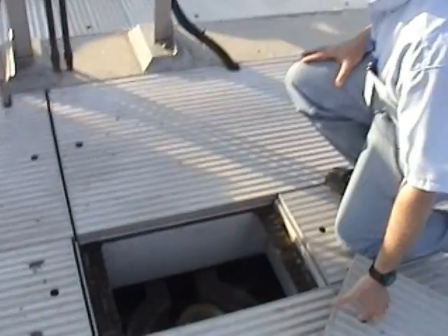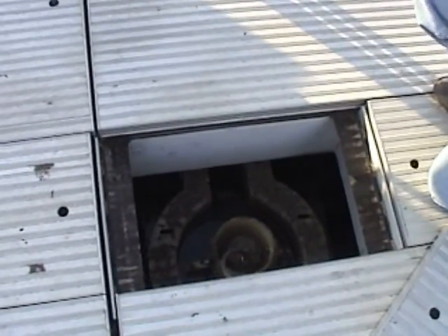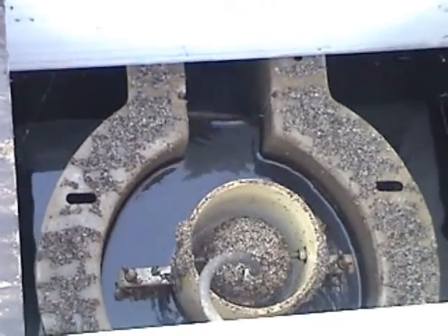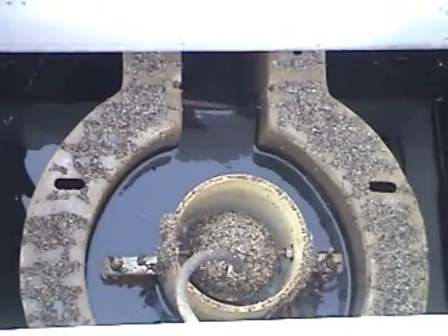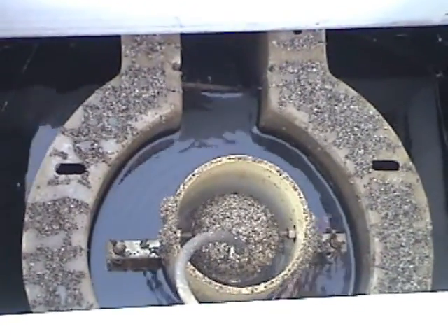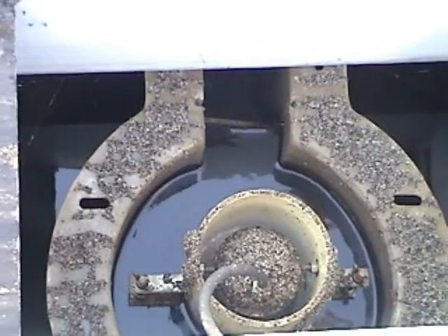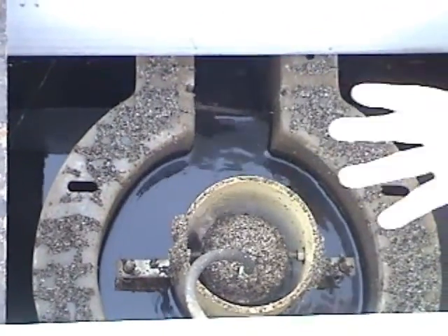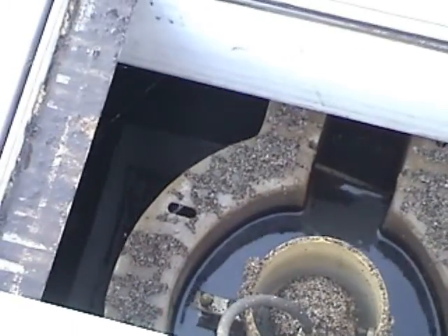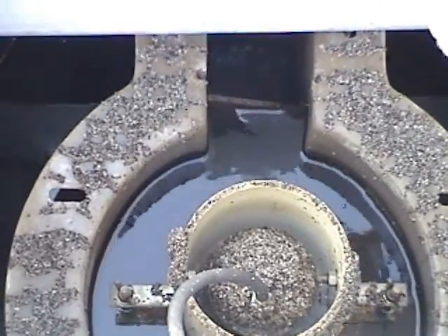What we're doing is we're taking our secondary effluent flow after we run it through the flocculators, where we add alum to it and mix it in, then we bring it over here and run it through a filter. And these are Dynasand filters, continuously backwashing. The flow is coming up from beneath the filter media, the sand that you see, and the water at the surface surrounding this circle right here is the effluent from the filter. The backwash water is the water you're seeing flowing over that little weir plate right there.